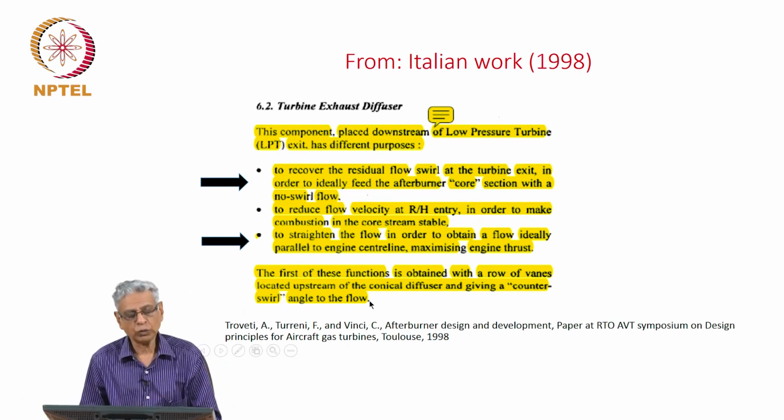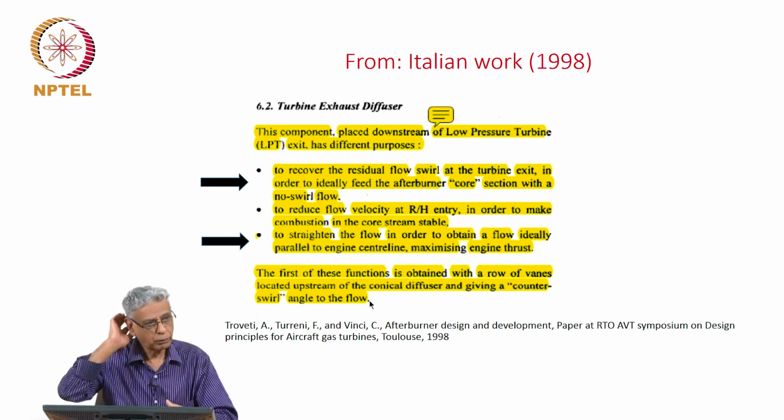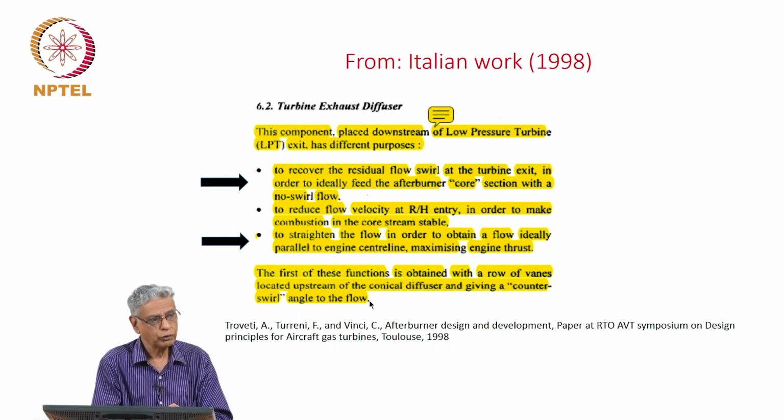The word counter swirl is used because any flow which comes out of the turbine will have a certain swirl. Because of the rotation of the turbine blades, you will find a swirl. So, you need to put in some effort of design to make sure it is axial. That is the statement made here.